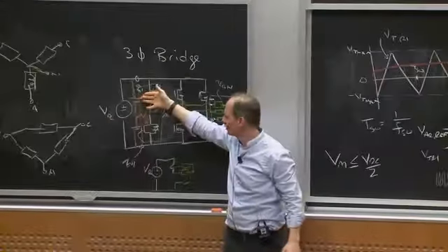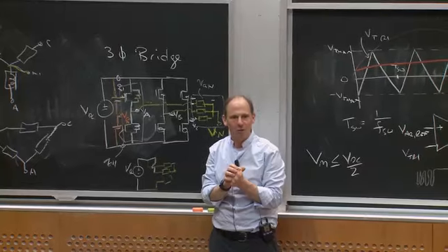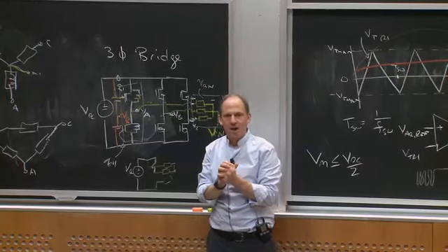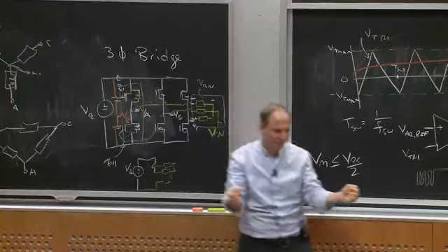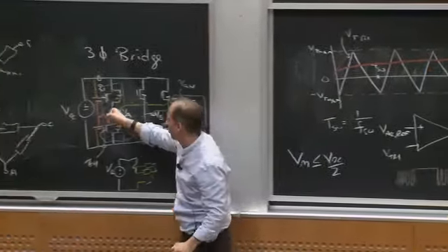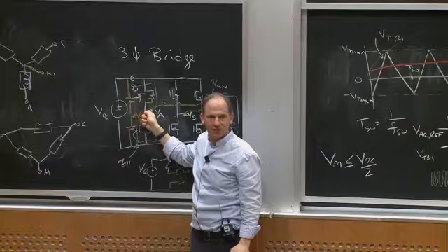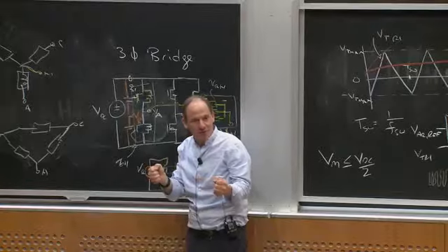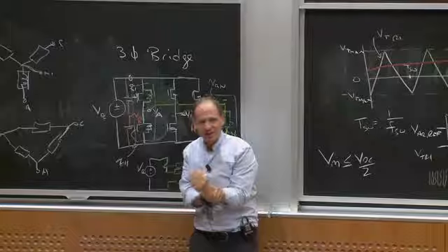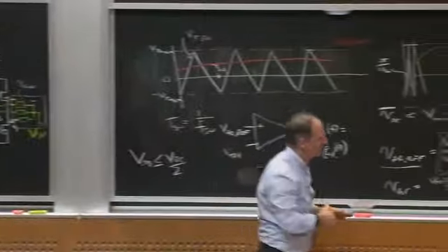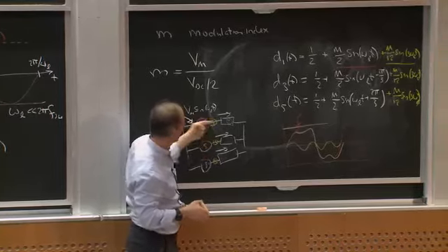He's going to be on for half the cycle. And you're back to the 6-step waveform that I talked about before. In that case, I really do generate the maximum fundamental. The maximum fundamental is basically, VAR is a square wave: VDC over 2 times 4 over pi is the fundamental of a square wave of amplitude plus or minus VDC over 2. That's the biggest fundamental I can synthesize, and that sets an upper bound on the fundamental voltage I can drive here.